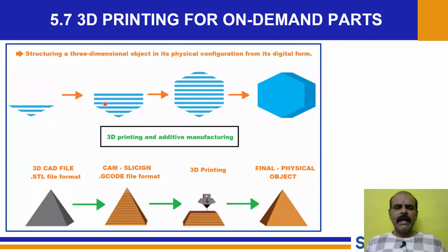So this is how exactly the product is made. We go ahead with the design, and whatever we want in the form of a digital design can be printed layer by layer. Initially we make the design and it is converted to STL. I want students to recall this STL: Standard Tessellation Language, tessellation, or usually it is also called stereolithography. From that we get the codes after slicing. Slicing parameters can be designed. It is going to print layer by layer, and finally we get the part. Maybe some post processing can be applied to get the aesthetics and appearance of the part in a good way.